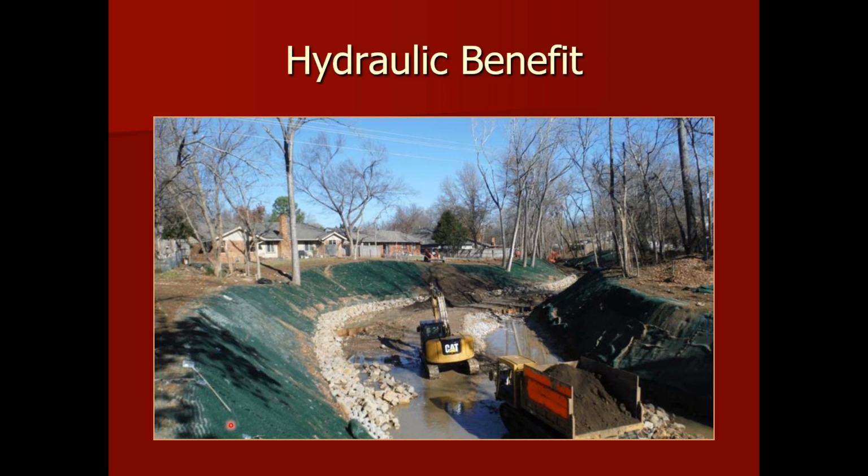You can see here this is a rather steep slope around this bend. So the anchors are asked to do two things. They're asked to hold the slope in place geotechnically and then provide hydraulic stability as the velocity accelerates around this corner. Important to notice, again, used with another form of protection here at the toe so that you're holding the toe in place and providing vegetated protection up above it.